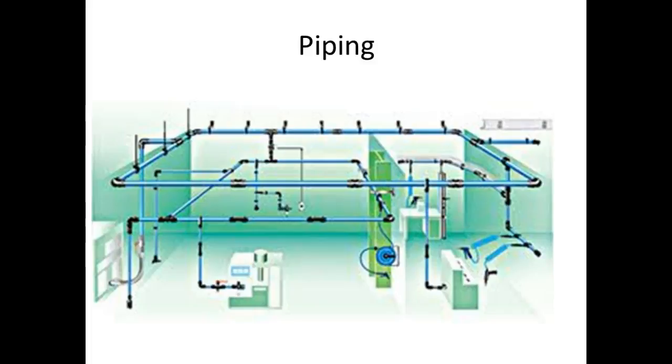Y'all understand that? So y'all probably saw that over there on your meter. You're sitting there and you're reading 60 psi. But as soon as you get flow, what happens? Yeah, drop. Because to have a pressure loss, you've got to have movement. And that's when we start getting pressure loss.